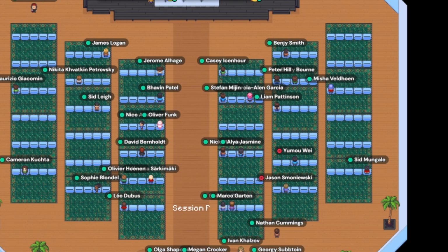Awesome, thanks. I have one short question, hopefully. Maybe it's actually probably a bigger question, but there are many different mesh element types that are supported in MOOSE, and I'm just curious about MOOSE's ability to cross-map those different element types. I know that, for example, in Cardinal, there's an intermediate mesh between the OpenMC domain and the NekRS domain, but like high order elements to linear elements and things like that, it's able to interpolate between those domains. Is that right? Yeah, so it can interpolate between those domains.